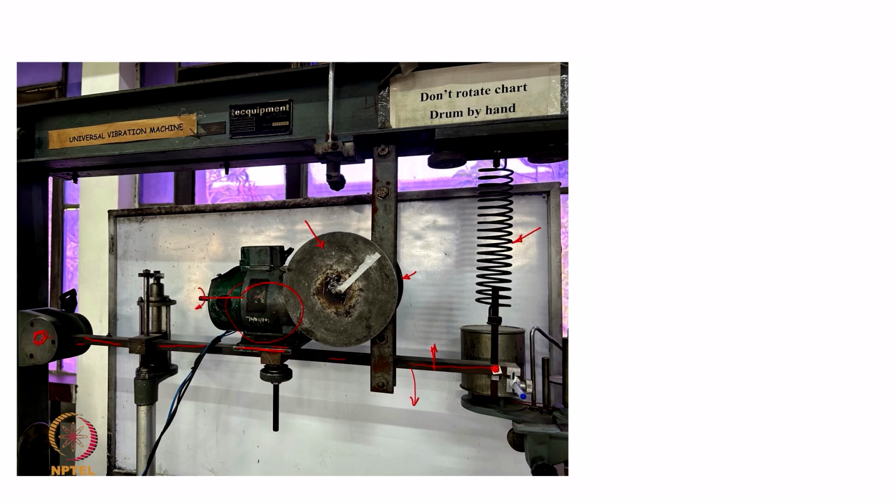The motor has its axis here, but it splits into two at 90 degrees through the gearbox, and then these discs rotate at some speed. More important is that the disc has a small unbalanced weight which is attached here at this location. So, the example of a forced unbalanced excitation is actually implemented here. In addition, you can notice a small dashpot, which will be clear in the next picture, that is also there to give some amount of damping to this oscillatory system. Okay.